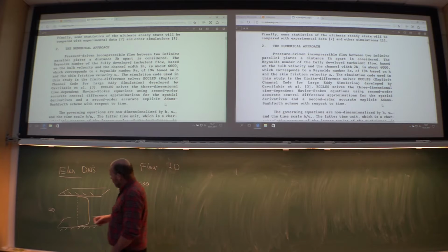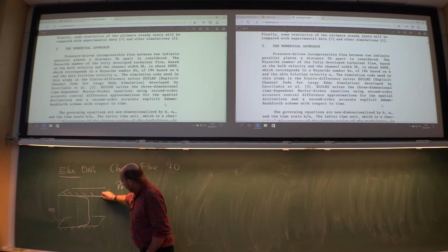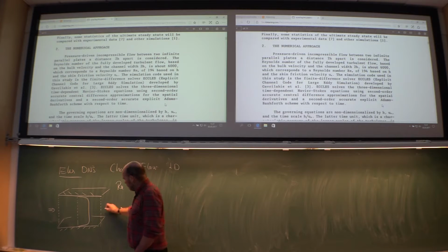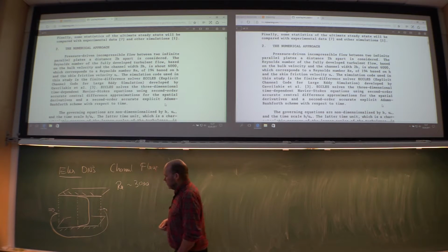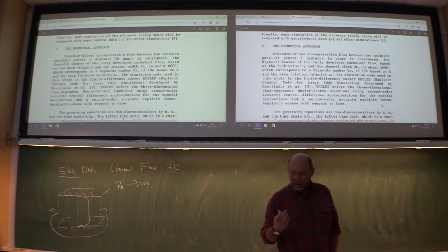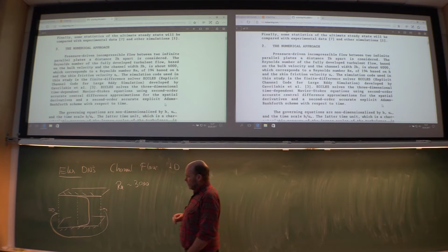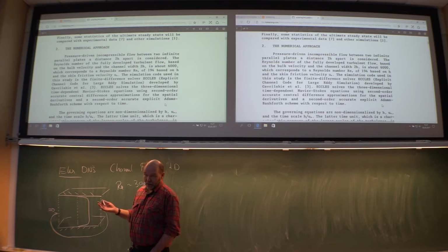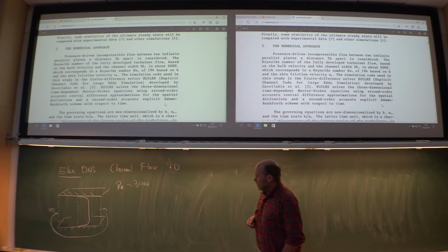So what you do, you take as an inlet condition whatever comes out here. So you use cyclic boundary conditions. So a velocity going out here, you just send it in on the other side, and vice versa. Same goes with the pressure, except then in the streamwise direction, you need a sort of driving force in the problem. You need a constant, it could be gravity for that matter. You need a constant term to have a force pushing the fluid through.